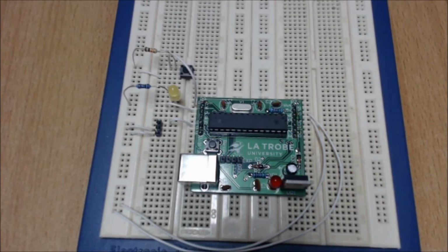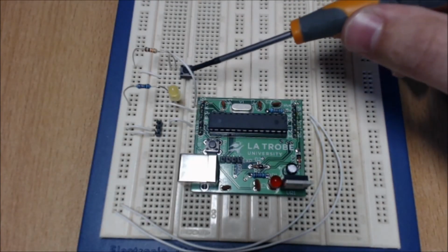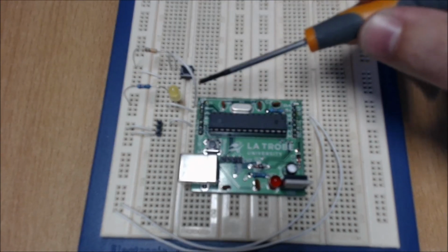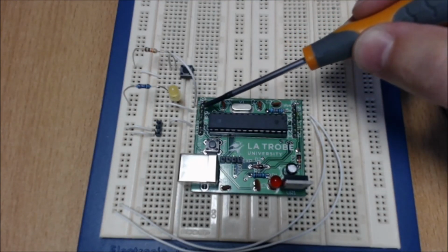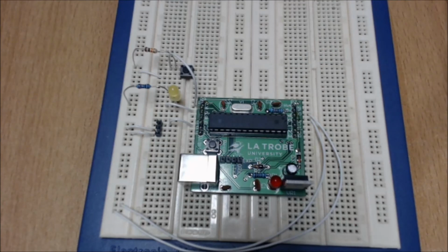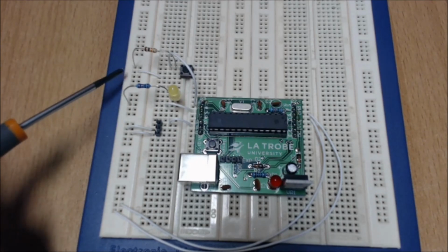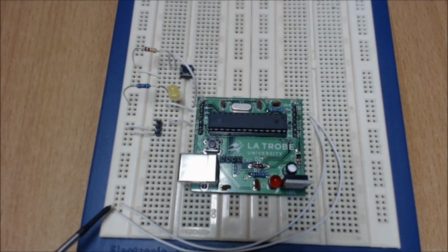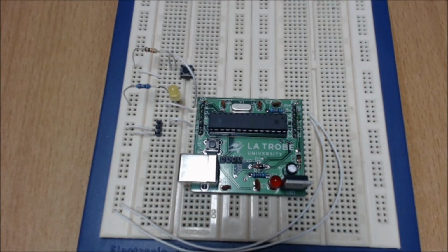So here we see our hardware setup for this exercise. We have our switch here connected into pin 5. We have our LED here connected into pin 6. And of course with our switch we have our 10k pull-up resistor, and with our LED we have our current limiting resistor as well. You'll notice along the edge here I've used one of these vertical planes for ground or 0 volts, and one of them for our 5 volt signal, and those wires just feed into the 5 volt and ground signals here. As all these are connected, it makes for an easy way to route our power and ground out to various parts of the circuit.